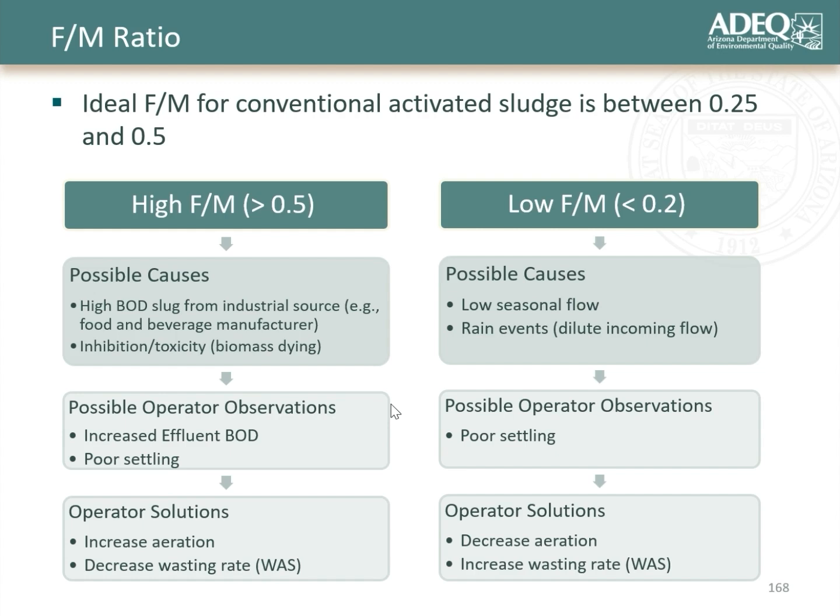The thing that the operator can do is increase aeration. If there is a high BOD, you can then provide enough air to make sure that the bacteria can grow and chew on that and eventually bring down that BOD.